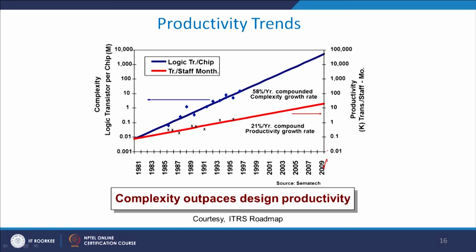Generally, clean rooms are marked as 10, 100, 1000, 10,000, and so on. 100 is the best one, because there are 100 particles per unit volume of that area, and similarly 10,000 will also have some particles. So, the lower the value, the higher the cost, both running cost and the cost of fabricating a clean room environment. This is a typical environment you get in a clean room.